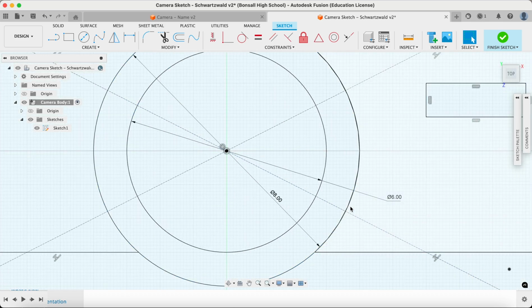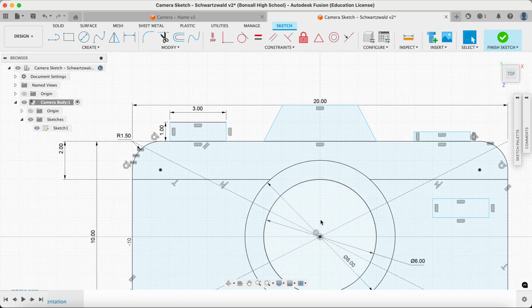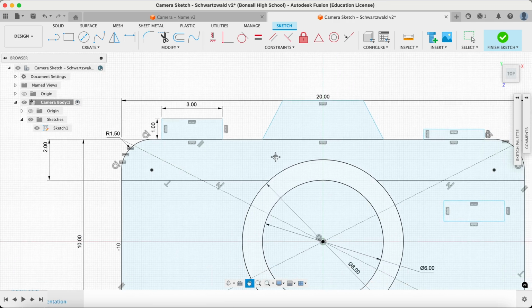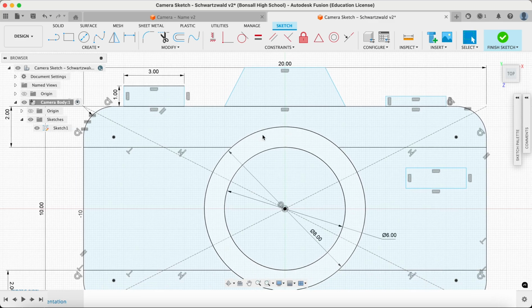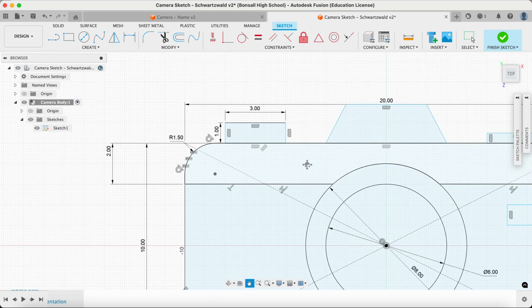which is why their lines appear black. Other elements that have not been fully defined will appear as blue. These blue lines need more information in order to fully manufacture and develop this particular product. To do that, we have to go through and ensure that all of them have their proper constraints and that they have been provided a position and a size.